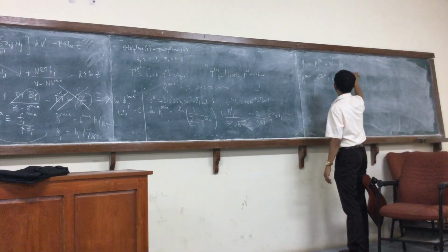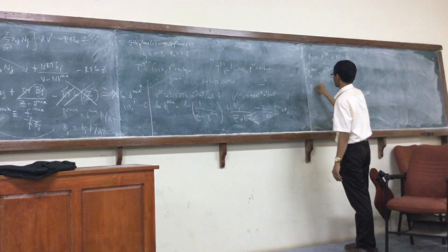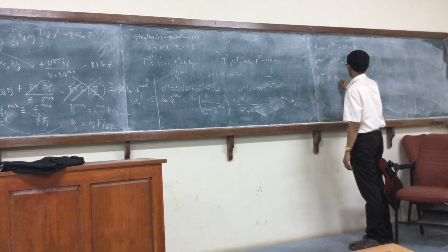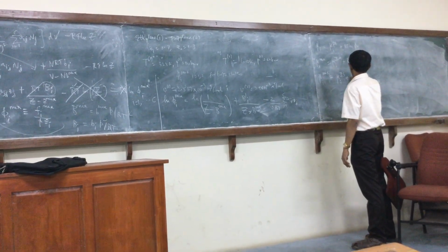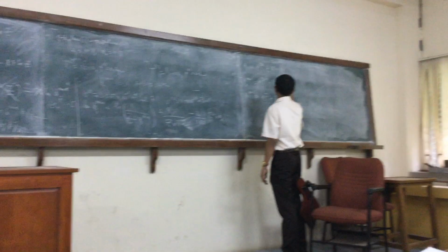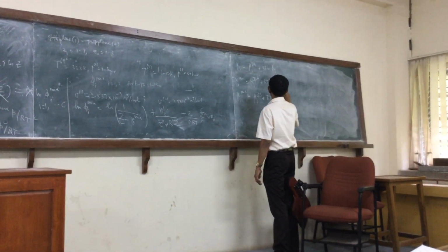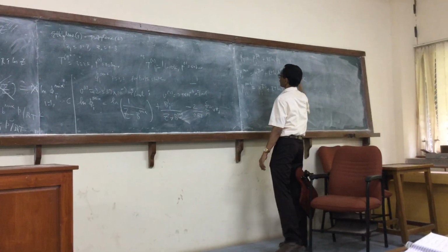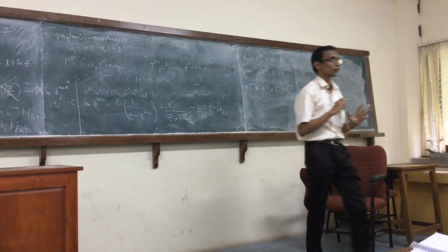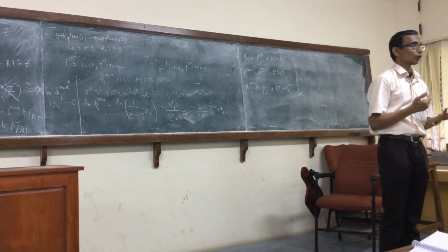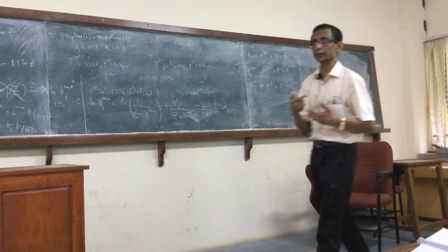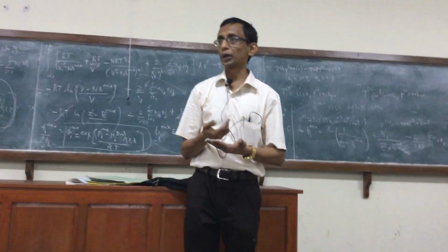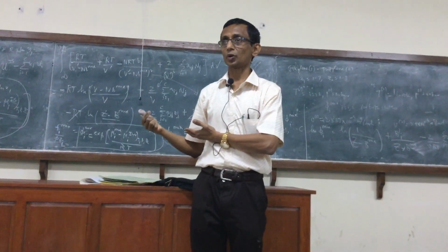Mixture, we have two different expressions. You see the significance of this when we do vapor liquid equilibrium. These, i equal to 1 to C. So you can see here the role of the fugacity coefficient for the pure component and the fugacity coefficient of each component, as well as the activity coefficient of each component in a mixture.